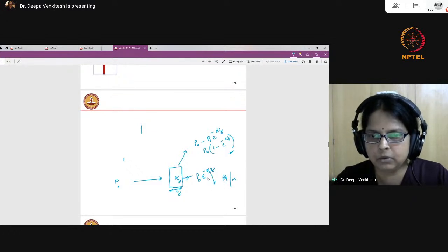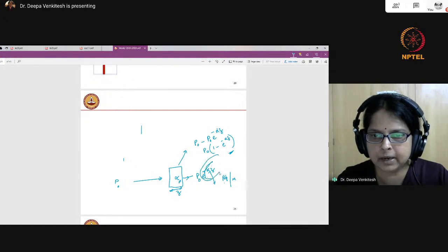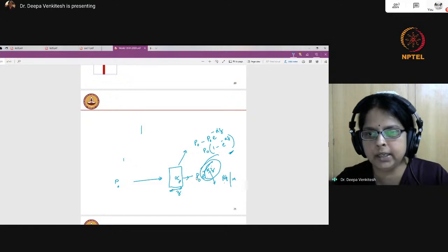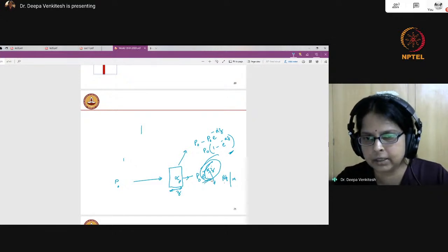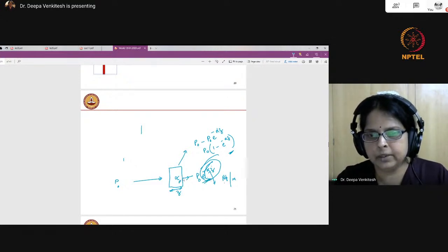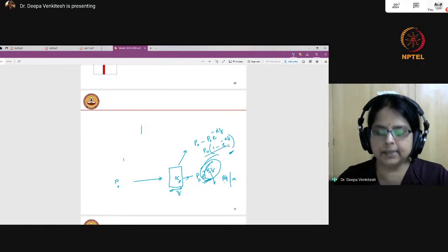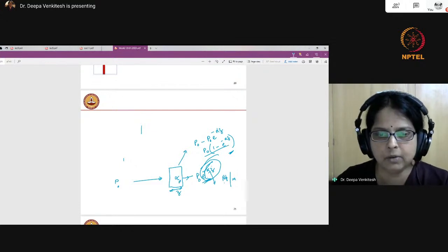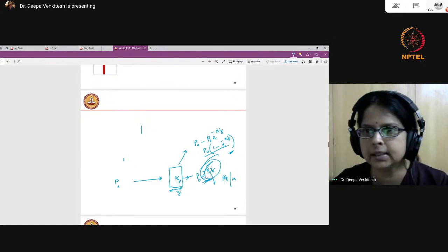And when you do an exponential with Nepers, this part becomes a dimensionless quantity, and this tells you the fraction that comes out. So obviously, what is absorbed would mean P naught into 1 minus e power minus alpha Z. If there was a mistake there, I apologize, and we will go back and correct that.